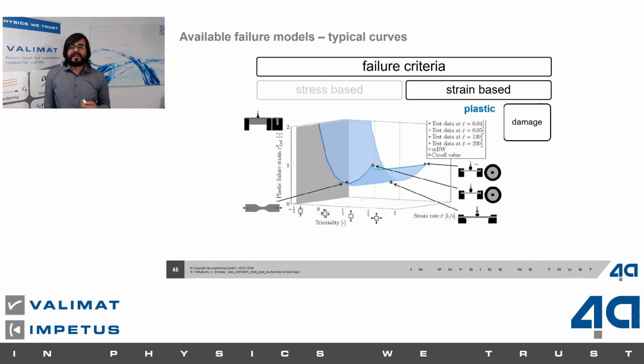So it is possible that we have different strain rate scaling for a different triaxiality. If we go very much in depth with modeling failure, then the more accurate way to approach it would be to have the exact values of strain rate scaling also dependent on the triaxiality levels.